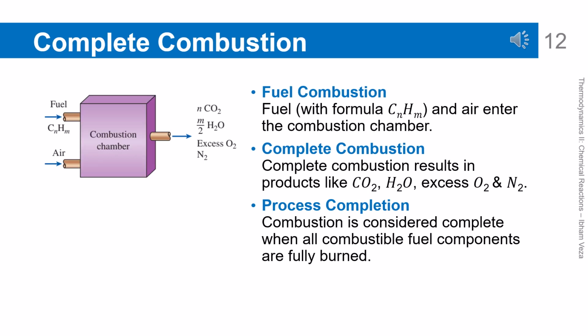Complete combustion. Complete combustion occurs when all the fuel reacts perfectly with oxygen. The products consist only of CO2, H2O, nitrogen, and possibly excess oxygen. No unburned fuel remains in the products. This condition represents ideal combustion from a chemical point of view. This concept becomes the reference for defining theoretical combustion and combustion efficiency.